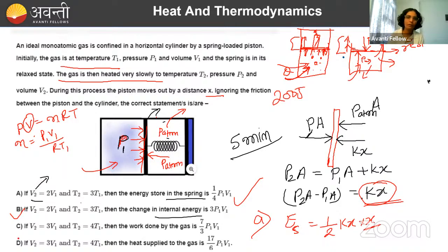Internal energy, whatever be the process, we have already written. Your concern may be how we will calculate the work done. If we don't know the process and nothing is given, it is polytropic but the power of x is not stated. We define a polytropic process as PV^x equal to constant, but the x value is not given. Nothing is said about the process, so we must adopt some other way to get the answer. And what will be that other way?